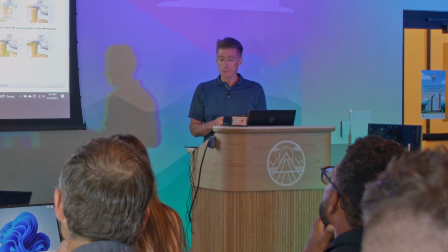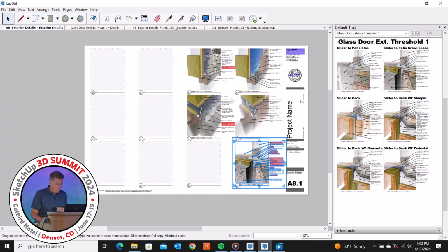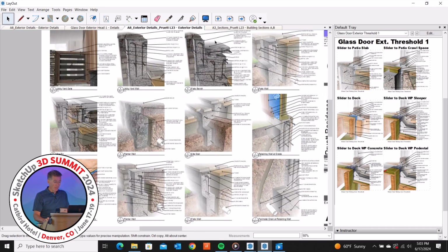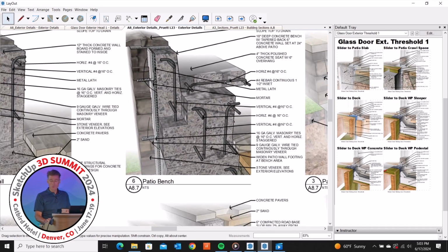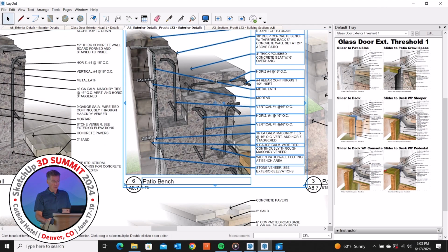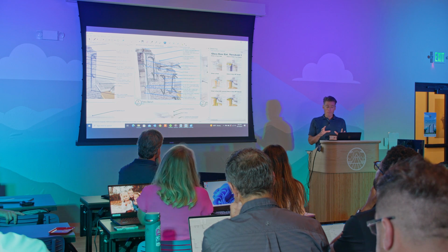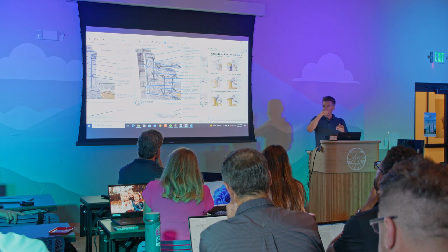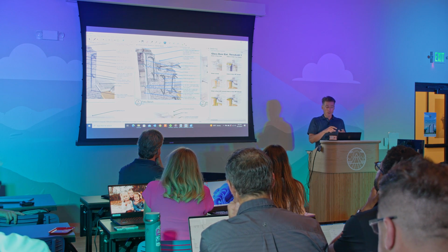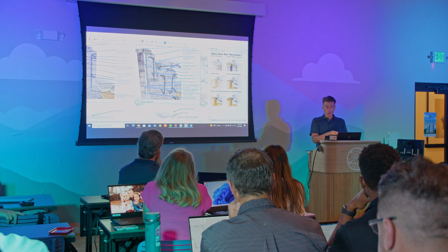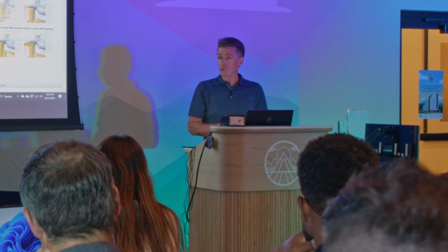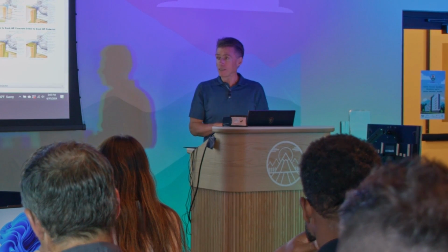Sometimes I'll do it as an individual detail, like I think I did on this bench, because if it's a detail I don't think I'm going to have again, I'll just leave it like this. You know, it's rare that someone asks me to do something like this. And so this detail was actually prepared here. I have a scrapbook details template, which I think I told you already, that just has notes on the side. They all just say group, group, group, group with an arrow. And then I just bring in the reference of the detail from SketchUp, and then I edit each note just by moving the arrow, and then I select the choice if there's multiple choices. If there's none, I just pick it and enter.